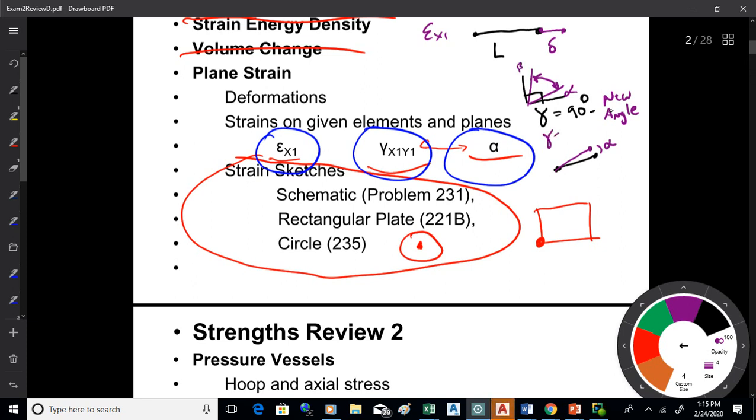Gamma is the sum of alpha and beta. I think it's important to understand the difference between alpha versus the shear strain. They're slightly different things. They're related, but they're not the same. To get gamma, you're starting with an angle and seeing how that angular measure changes. To get alpha, you're just looking at how a line rotates. We're good?